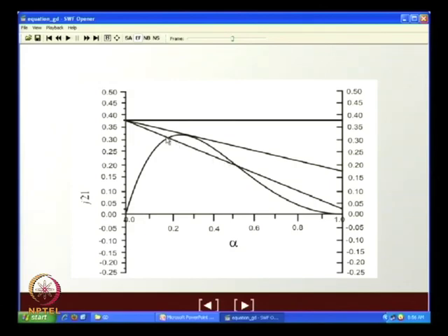What does it denote? Bubbly flow, liquid higher proportion, gas lower proportion, and high alpha sort of a droplet flow, or maybe annular type where droplets are dispersed in the gas core. Clear? So, therefore, one solution you get at a low alpha, other solution you get at a higher alpha. Clear to all of you?